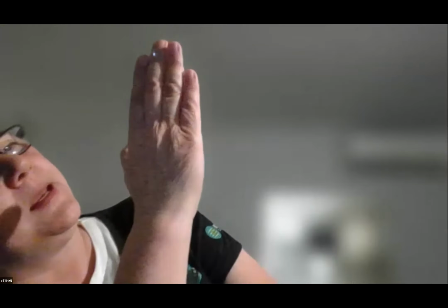Another indication might be, if you look on the side of the wall, it's sometimes very hard because visually you might not see water mist on the surface of the material. But sometimes when you use your torch on the side, you might be able to see watermarks, and that will also tell you that there's condensation within that wall.